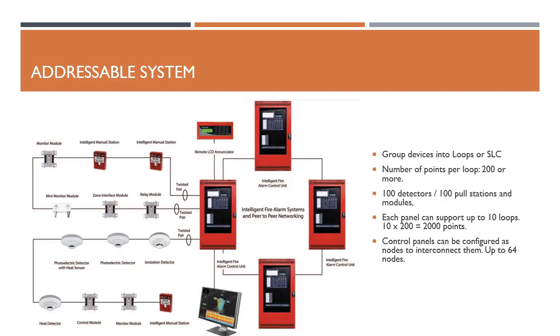Now, for notification, the addressable panel has NACs also, as the conventional panels do. But we can also connect horns, strobes, and speakers through addressable control modules that allow us to divide the notification loop into floors or sections. For example, if in a building the fire department requires that in our design any alarm only activates the horns of the corresponding floor where the signal came from, the selection of this type of control module is what we need to achieve it.